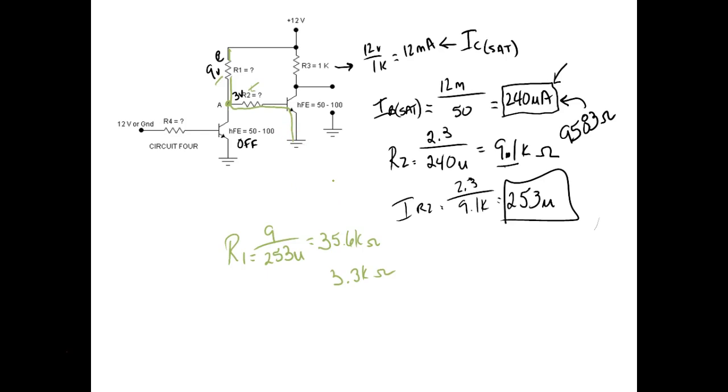It's saturated. Okay, guys, what we're going to do is cut this transistor off. This transistor here is going to cut off when this transistor right here cuts on. So what's going to happen when this transistor cuts on and saturates, that's going to bring 0 volts and put it right there. 0 volts is right there, right? You understand? Everybody okay? So with that 0 volts, I have no base current. This guy here is no longer going to drop 9 volts. When it's saturated, it's going to jump up to 12, because now it's dropping all the voltage, right? You understand? So what size would we use for R2?